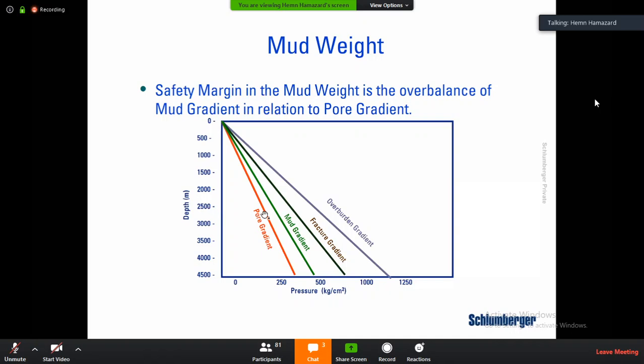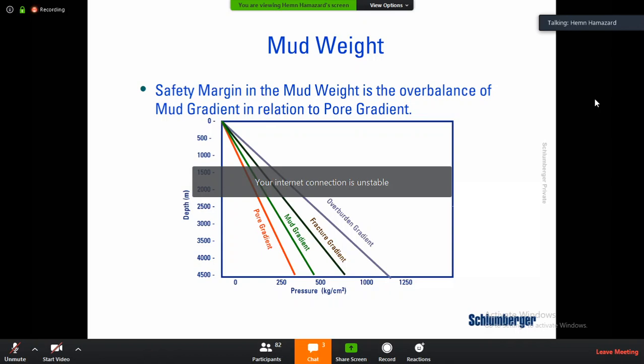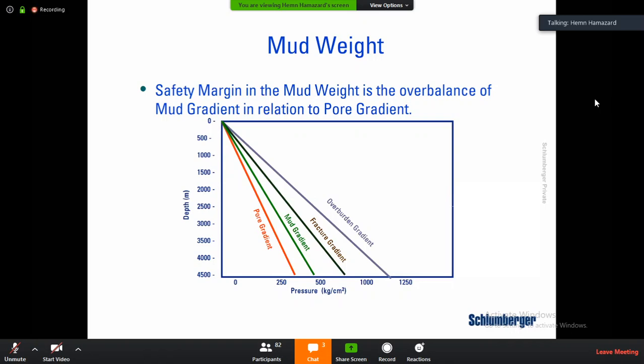You cannot be below this, you see the mouse cursor. On the other hand, you have the upper limit, which is the fracture gradient. For many wells, especially development and appraisal wells, we do a test they call LOT or FIT. We don't need to go into that detail, but in most cases you know your maximum limit for the fracture gradient and your minimum limit. So your mud weight should be in that window. Okay, so that's how you pick any mud weight.